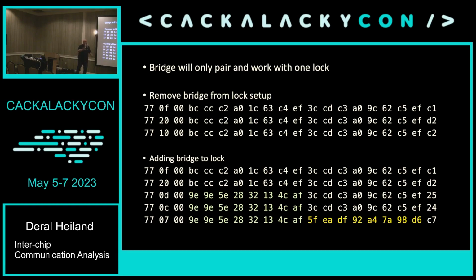That lasted for like 20 minutes, and then the system reset itself, got rid of the old lock, the first lock in, and kept the new lock. Interesting behavior. So this is some of the behavioral testing we've done, trying to figure out how a device handles security. In this particular case, once a device is configured, the command coming from the cloud all the way to the lock never changes. It's never readdressed, never rekeyed. It's always the same. So if that data is compromised, obviously the level of compromise here is way complex because it's inter-chip related. But it's always tied back to the actual device's key that's on the device.